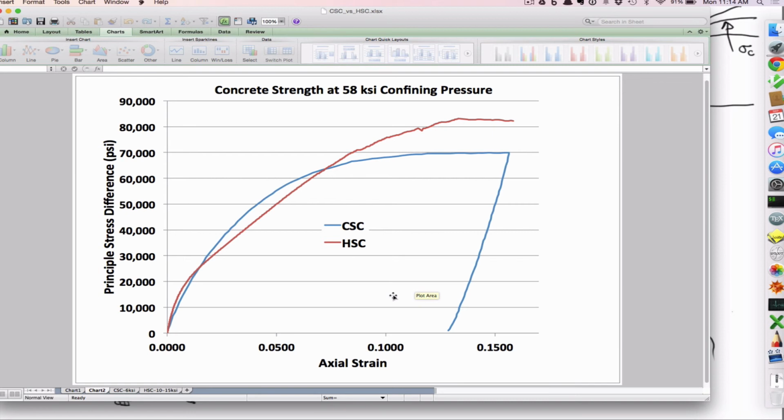You can almost never get the right elastic modulus on the initial loading of any kind of geomaterial, because you have small flaws and other gaps in the material that are taken up when you initially confine it. You have a little bit of slip on the planes, on the little cracks and micro flaws that are in the rock. So you can almost never get the right elastic modulus on the initial loading, and we usually don't even try. Usually what you get it from is the unloading cycle.